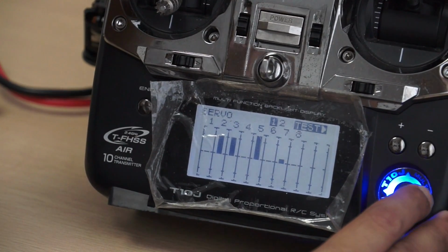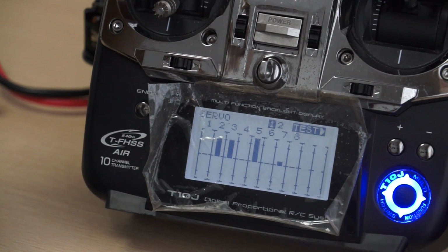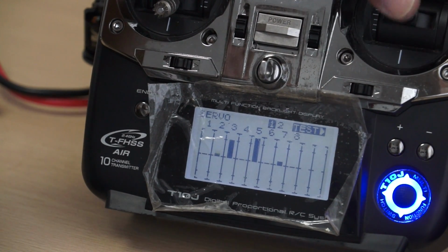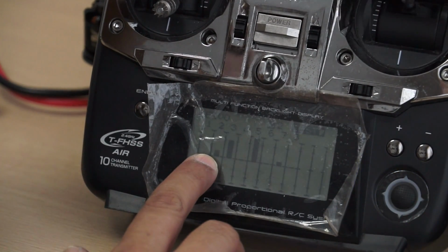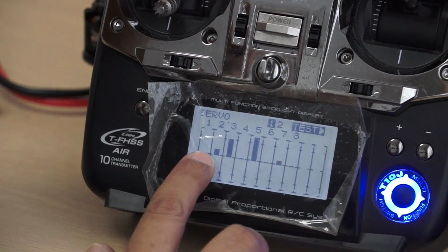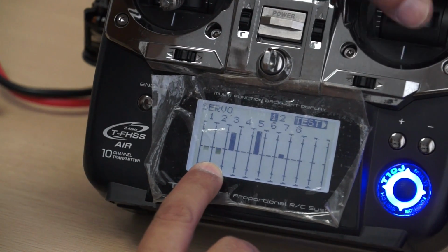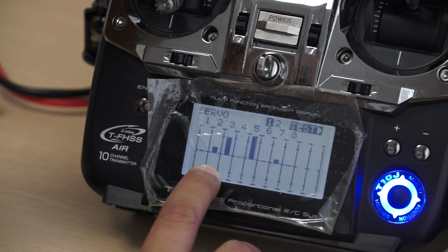So what I want is the quadcopter to tilt rotor, but this effect reduced. So I turn on the second mixing, and you can see suddenly my elevator right here, this effect is reduced a lot. You can see, because I'm using minus 65 values. So either up or down, my elevator effect is reduced a whole lot.